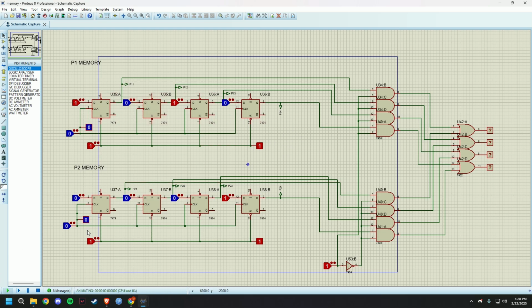So what will I need? I will need a 1 signal in the clock signal of all these D-type registers. So whenever the clock signal goes from 0 to 1, this 1010 position will get passed down, and through these AND gates and the OR gates, this is acting as a demux. So whenever the player signal from the player selector module is 1, then this player 1's position will get passed down to the current player's active position output.